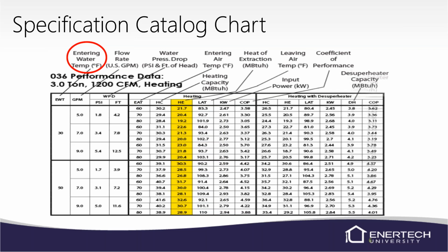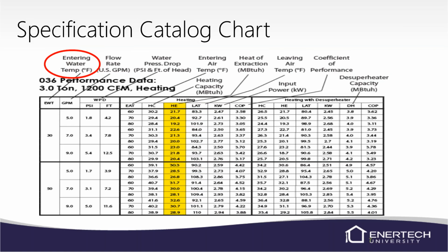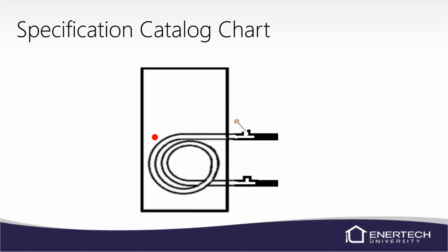That's the entering water coming into the unit. Basically, we put a pressure or temperature gauge in the entering water and check the temperature of that water. I will say real quick, we do sell a Cooper thermometer, and it's got a tapered end on it, and it's real small, so it goes into those PT ports really nicely.